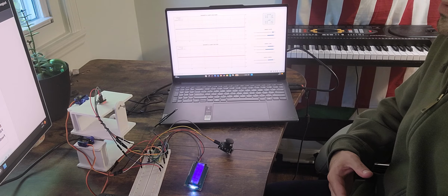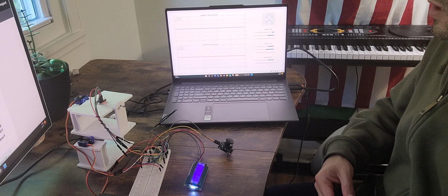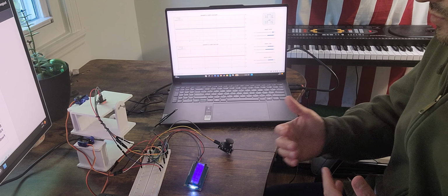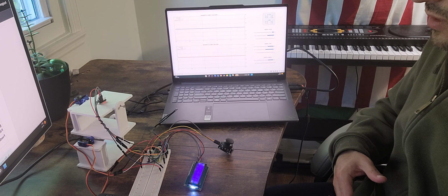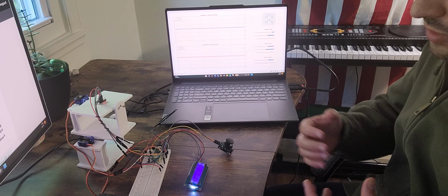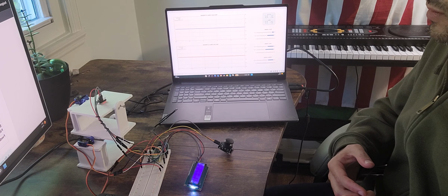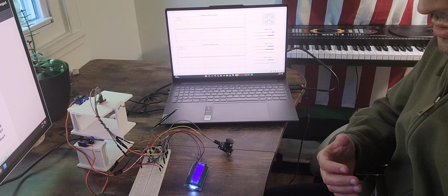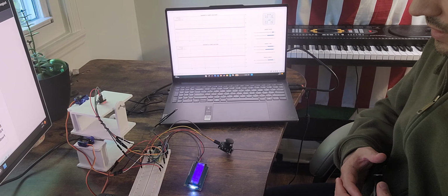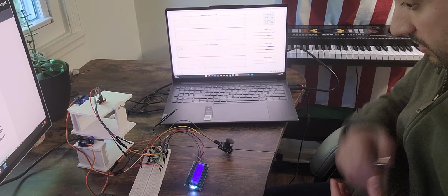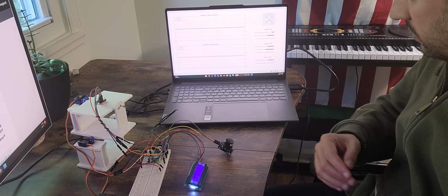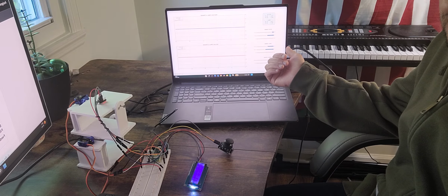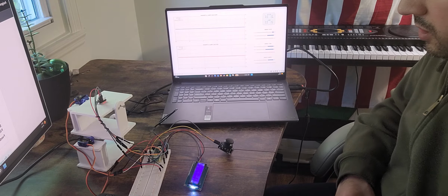And then for the state estimation, as I mentioned, I'm using a complementary filter to filter out the noise from the accelerometer and also filter out the drift of the gyro, and then fuse them together to get a more accurate representation of the measured angle. That complementary filter is implemented there to fuse those together, and the tau coefficient of it can be set using the dashboard.